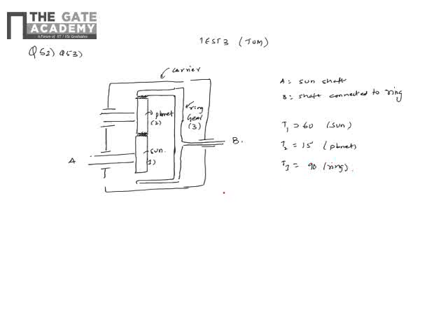Okay, and what is given is that the speed of the input shaft A is 1800 rpm. The input is given to A, output is taken from the carrier C, basically the arm, and shaft B, or basically the ring gear, is stationary. Shaft B is stationary. Okay, so how do we solve these kinds of problems?